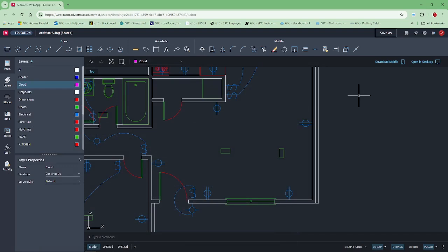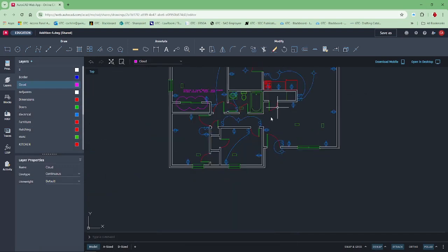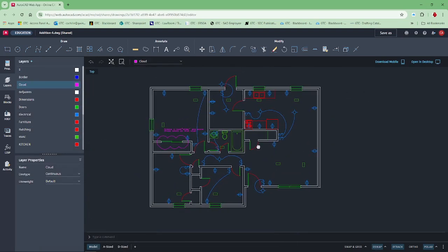In this practice, you will use a shared drawing and create an overlay trace. You will use the trace tool within Autodesk AutoCAD web app to make multiple markups. Finally, you will display the shared drawing trace markup in the AutoCAD software where you can respond to any changes from the trace. You have a shared drawing, Edition-A, already open in the Autodesk AutoCAD web app.